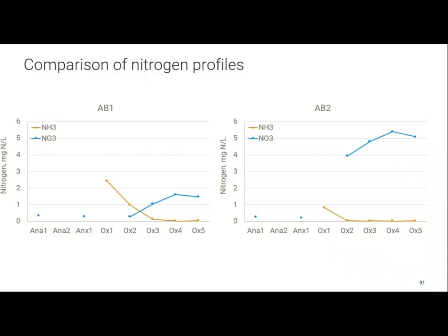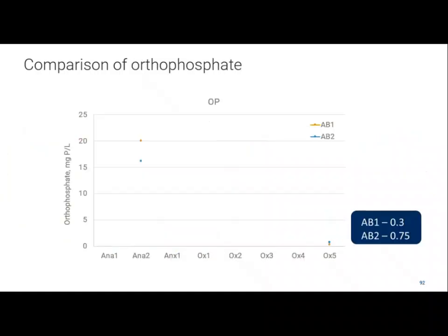Yep, because why? Why does low nitrate mean your sludge blanket's going to go anaerobic faster? Not nitrify. Put two letters in front of that, nitrify. There we go. Going to denitrify. There's less nitrate to get rid of before it goes anaerobic, and that could be a good or bad thing, right? But it's just something to be aware of, that if you see changes in your sludge blanket dynamics, check out the nitrate concentration in your mixed liquor, and take that into consideration when you're targeting your sludge blanket thickness.